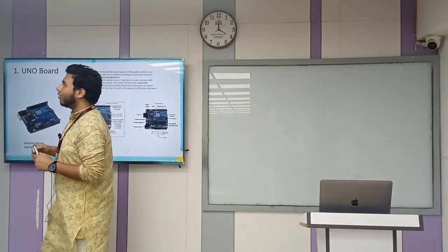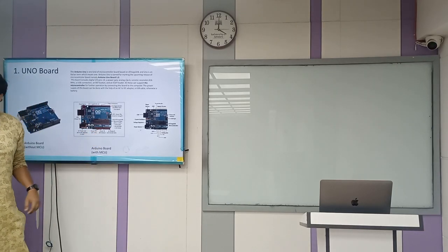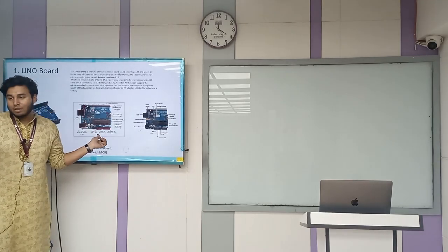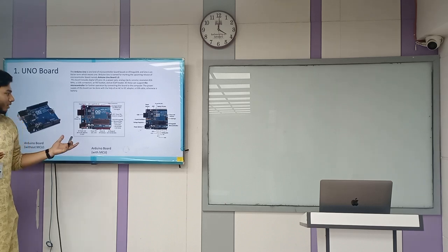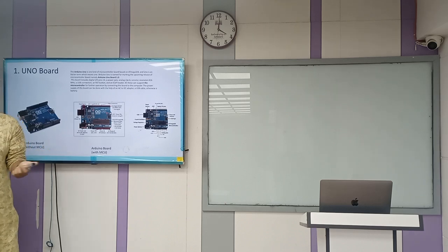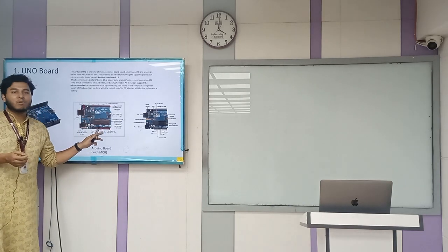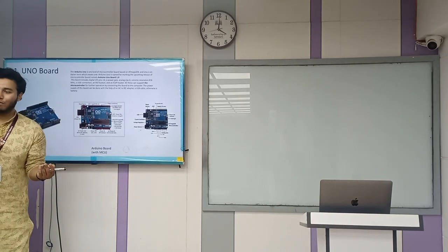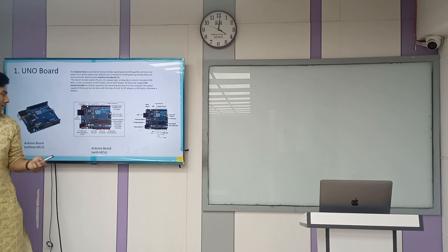It's possible, but the fact is the 5 volt port operates at 5 volt. So 4 volt, 5 volt, 5.5 volt will be okay. But when you connect the 9 volt to the 5 volt port, then the Arduino most probably loses its power, and you can't operate the other tasks with the 5 volt port. So the Vin port can be operated with a long range from 5 volt to 20, 18, 16, 15. So that's the fact.